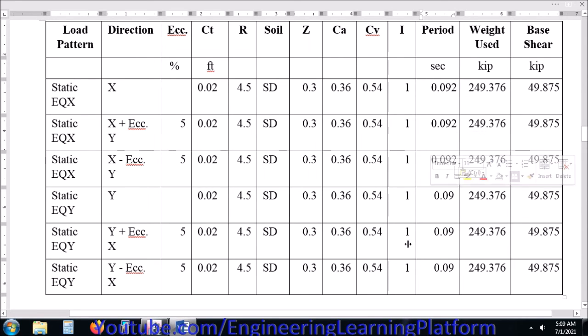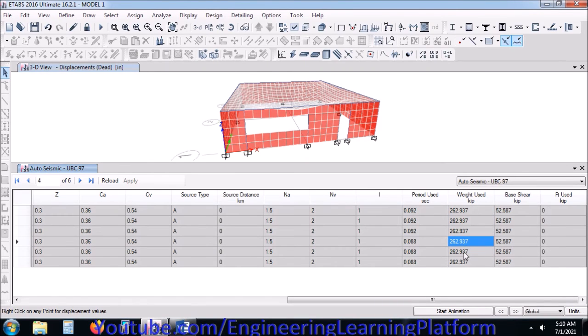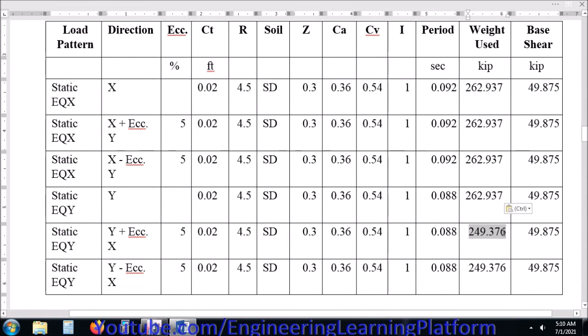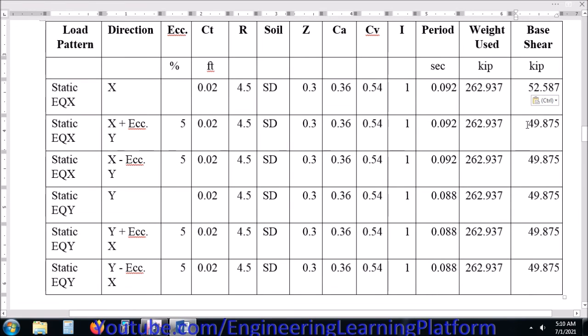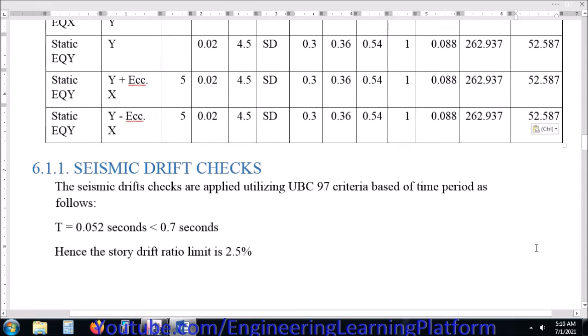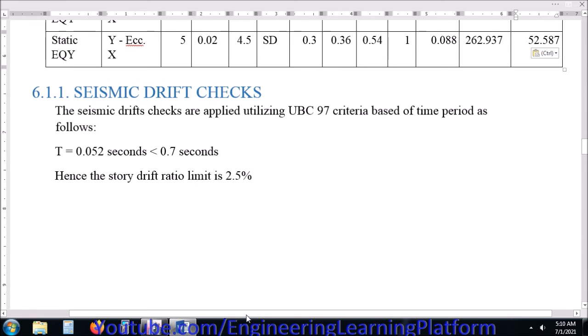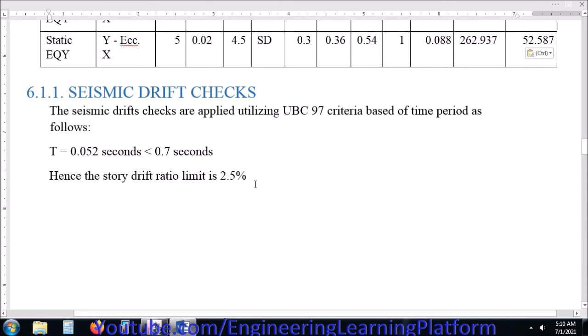As per the first modeling, the spans are quite large for a masonry structure. So there are large deformations in the slab and large force transfer from the slab to the walls. So definitely the stresses in the walls will be exceeding, which we will check in the next part. Similarly, we'll perform the checks for seismic drift,